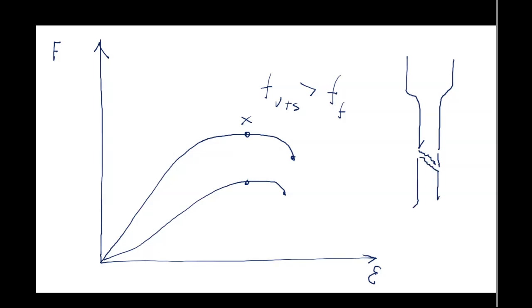and you would need to take dimensions at the thinning area. So somewhere really at the necking area, you take the width, you take the thickness, and you will also take the gauge length at fracture. By that, you would be able to proceed later with running the tasks in the lab.